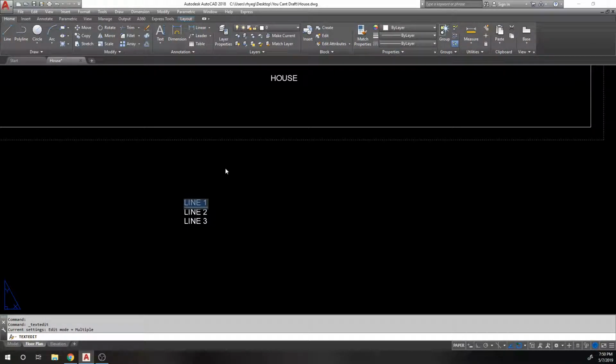I say hidden commands like you can use Ctrl+U to underline. You cannot use Ctrl+B to bold or Ctrl+I to italicize, but you can use Ctrl+U to underline. You can enter codes that are special to AutoCAD, like U+, actually, what do they call them? Unicode characters. I use U+2104 every so often. Arial apparently does not display it, but it creates a centerline symbol.